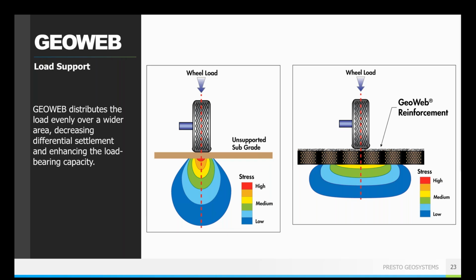The unreinforced section shows your typical stress distribution curve with your highest stresses at that interface between the tire and the road. And that load is dissipated over a typical unreinforced 45-degree load distribution angle, makes that stress bulb under there. Anybody who works in roadway design would be familiar with this. It is not anything new, unfortunately.